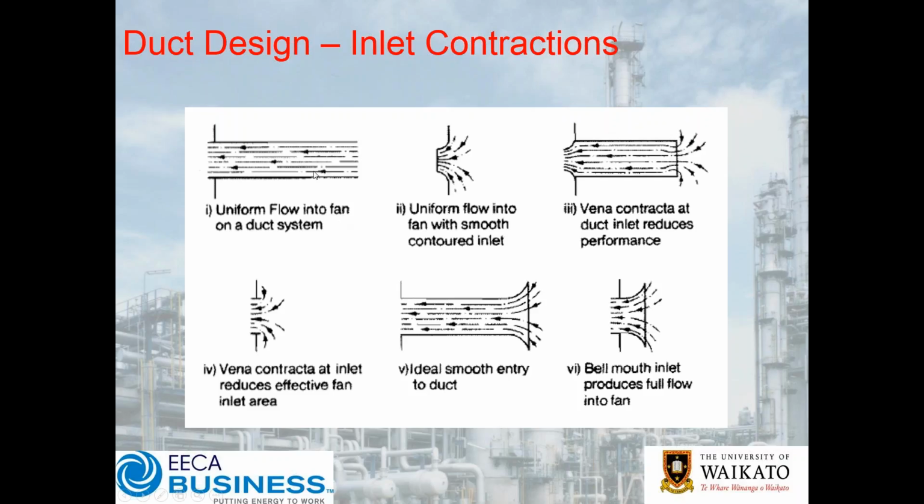So if you look at the top here, on the top left, we've got a nice straight inlet coming in. Obviously that's nice and ideal for the fan. Now the other option, if you don't have a big long inlet duct, you can have a nice swept curve bell mouth, also nice and good and efficient.